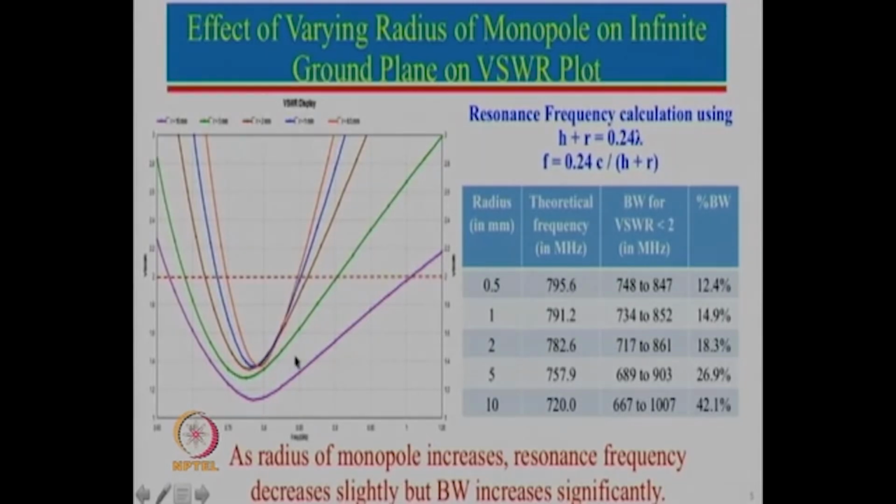So, you can see now here, as we increase the diameter, this is now the response. Frequency is slightly decreasing, which is expected over here, and you can see that the bandwidth is increasing. Now, recall I did mention for a dipole antenna that bandwidth is proportional to the diameter, but there I did not show you too many cases, but here we are showing you systematically the cases for monopole antenna, which is also valid for a dipole antenna.